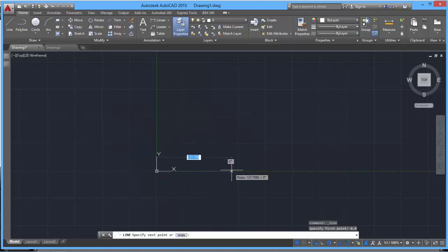Then I've got some choices. I can move it to a specific angle. So because I've got the 30-degree polar track set, I can set it to 30 or 60 degrees or 90 degrees and leave it on that track line. Now, regardless of whether it says 30 or not, unless you're seeing that track line, it's not probably on 30 degrees. And then I could enter a value, say 150, and that's in the box, and then hit enter, and that's going to give me a line 150 mil 30 degrees up from this horizontal line.